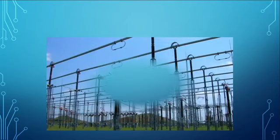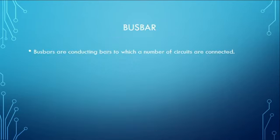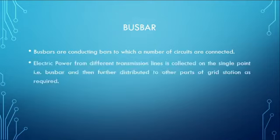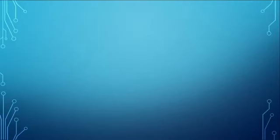Bus bar is another important component of any grid station. Bus bars are conducting bars to which a number of circuits are connected. Electric power from different transmission lines is connected on a single point, that is the bus bar, and then further distributed to other parts of the grid station as required. Bus bars can be arranged in different ways, that is single bus bar single breaker scheme, double bus bar single breaker scheme, 1.5 breaker scheme, etc. We will explain these schemes in detail in upcoming videos.